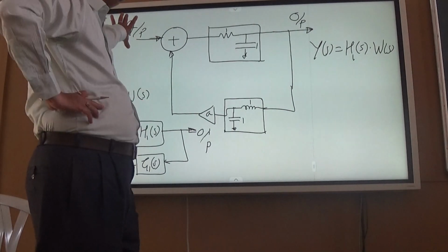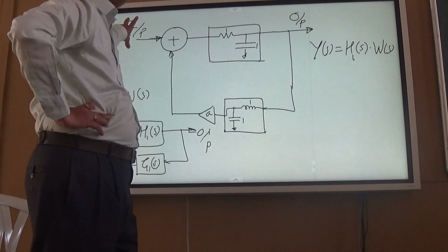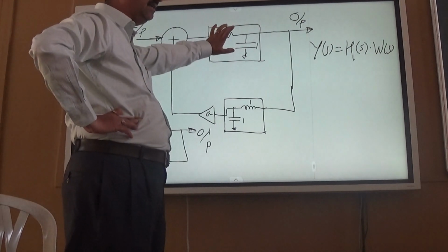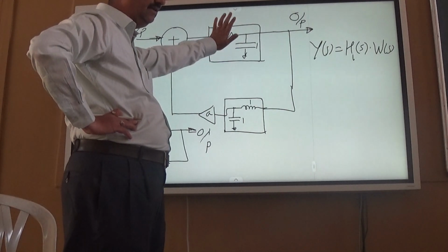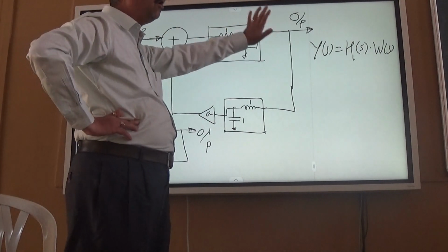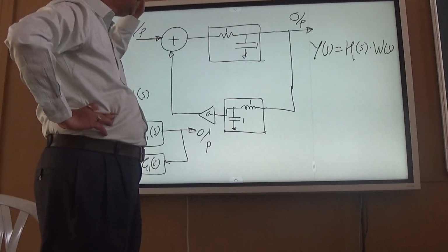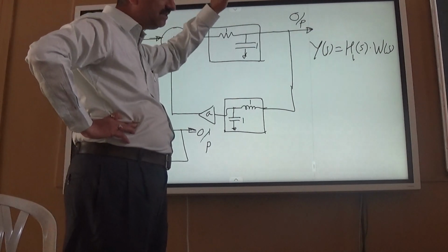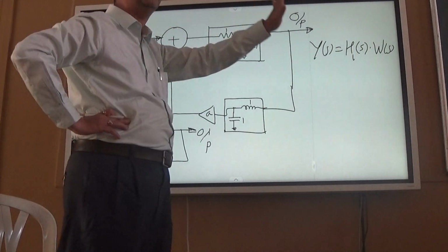when we say input in terms of s, it is the Laplace transform of v in t. The S-domain transfer function tells us that if input is e raised to st, output is that into e raised to st, or if I apply an input whose Laplace transform is X(s), then the inverse Laplace transform of Y(s), which is equal to X(s) into H(s), would be my output.